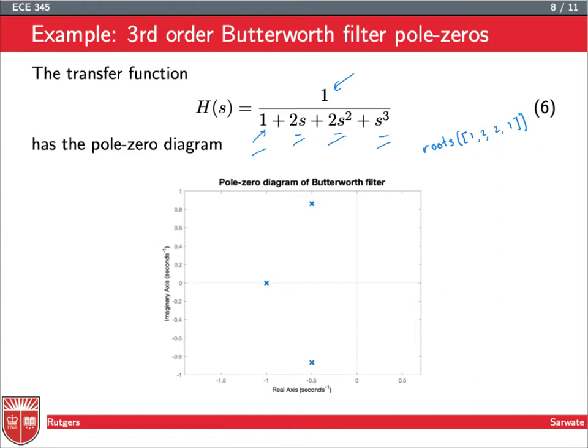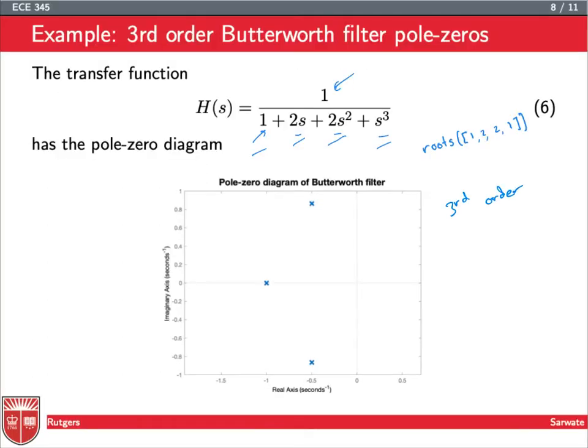So this Butterworth filter is, remember, third order. Third order means three poles. And here are the poles. If you think about it, you can see they're arranged in a sort of semicircle. And when we look at other examples of Butterworth filters, we can see a little better how cleverly the poles are positioned in order to get the effect that you would want.